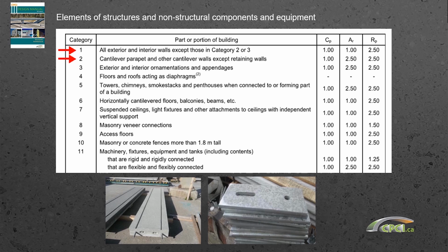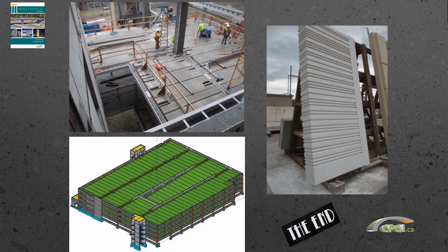And then basically, the seismic provisions in 2015 NBC have been totally changed. Still, the manual provides the basic guidelines for you to look at how to apply those provisions to precast structures, whether it's a hollow core or double T parking garage or hollow core building or architectural cladding. So it's a very good reference to assist engineers with looking at how to design precast concrete structures.